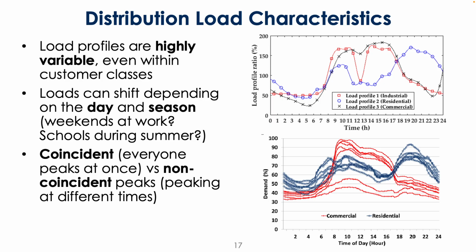And that can also change over time as well, which is one of the things that might be a challenge, right? Maybe I've designed the layout and built out a specific infrastructure on my distribution network to handle a particular type of load profile, but now suddenly everyone's driving electric vehicles and you have big load spikes at night, which it wasn't designed to handle. So the load shapes of these things and the corresponding implications on the distribution system are going to be an important thing to consider. They also change temporally, right, depending on day and season, to say nothing of these larger scale transitions.